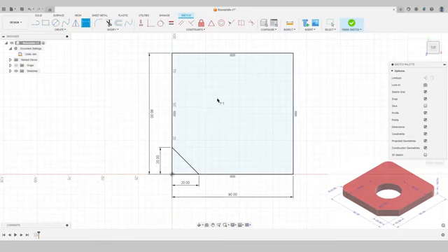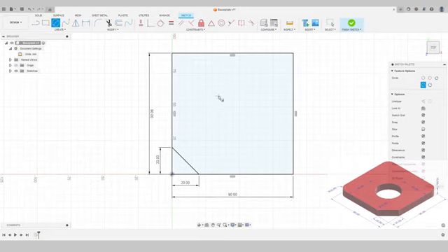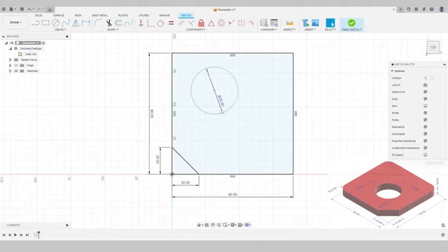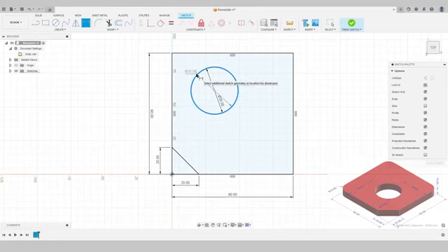Now we've also got this through hole feature, which is roughly in the center of this square. Let's go ahead and select the circle tool. I'm going to input this circle anywhere for the time being. The diameter is 35 millimeters, press enter. I'm going to use the dimension tool again to dimension this accordingly. So we'll see that it's blue in color now. We want that to be black, so it's not going to move anywhere.